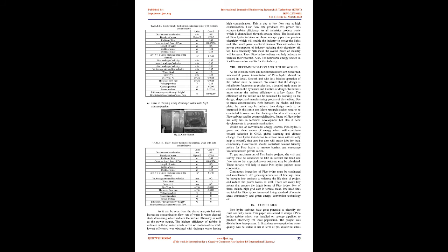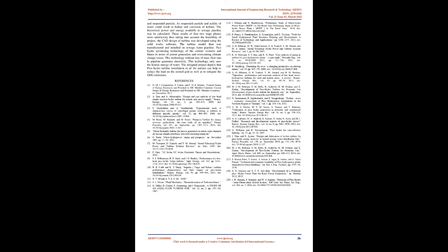8. Recommendation and future works. As far as future work and recommendations are concerned, mechanical power transmission of Picohydro should be studied in detail. Smooth and less friction operation of the turbine must be ensured. To ensure that the design is reliable for future energy production, a detailed study must be conducted on the dynamics and kinetics of the design. To harness more energy, the turbine efficiency is a key factor. The efficiency of the turbine can be enhanced by working on the design, shape, and manufacturing process of the turbine. Due to stress concentrations right between the blades and base plate, a crack may be initiated, thus the design needs to be improved in this sense too.